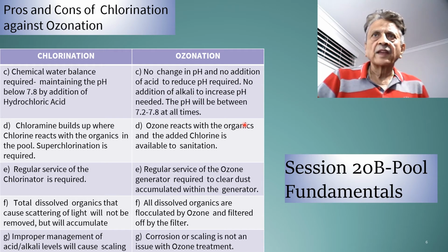However, if there are chloramines in the water, because, for example, it was used with chemical treatment prior, it is necessary to superchlorinate the pool to ensure that there are no more chloramines, and then proceed to ozonation, because ozone will not destroy or break up the chloramines, but ozone will prevent the formation of chloramines.